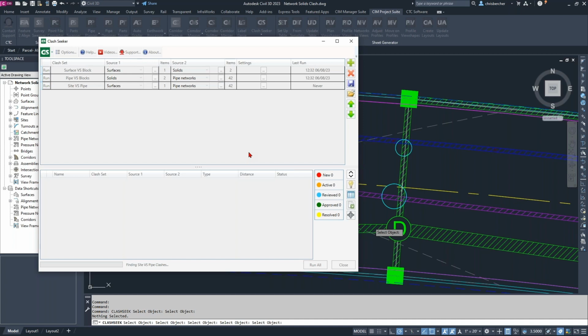You've got a really big site, and maybe you've got a lot of pipes, big surface, multiple surfaces, so it's nice to have those reminders every now and again. And you'll see the status bar will update down here. It'll tell you exactly which clash it's looking for at the time. So you'll start to gauge which one's the set that's going to take the most time. So it'll give you some of that information as you're going through it, and hopefully set some expectations a little bit here. That's the whole point of that. Otherwise, it looked like it was locking up on you, so we don't want that.